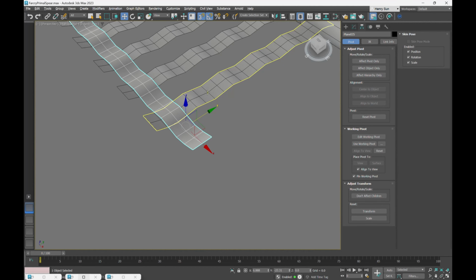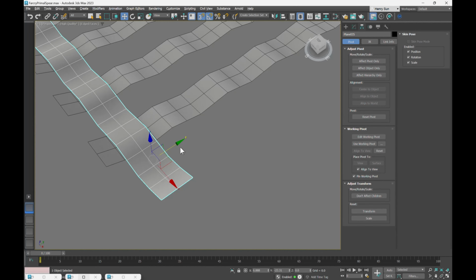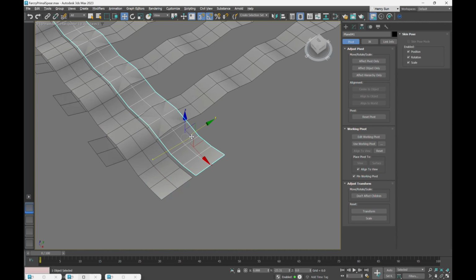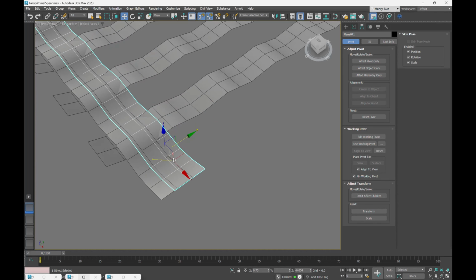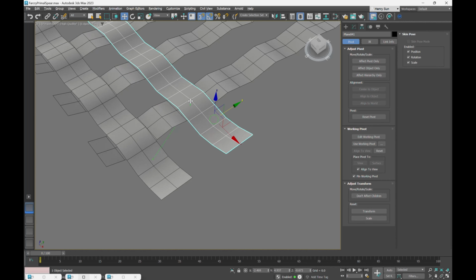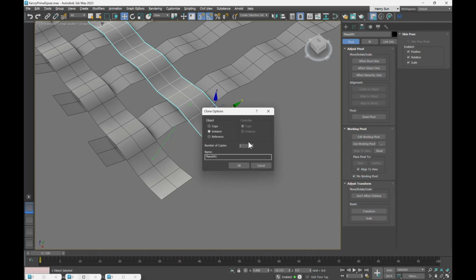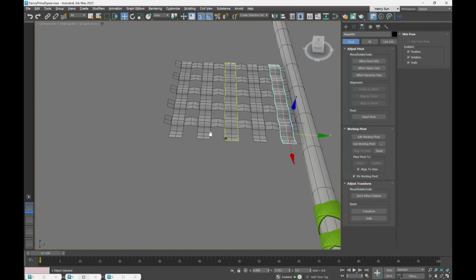So this is the center point that we need this to be snapped to. So let's hold down shift, move that down in the Y, and I'm moving my cursor over that point. And because I have axis constraints on, it's behaving the way I want it to. Great.